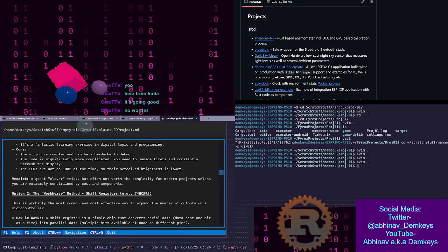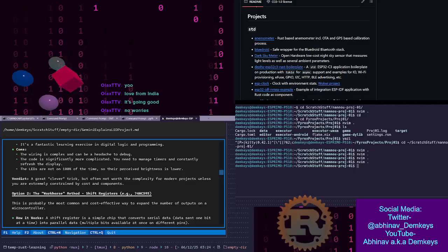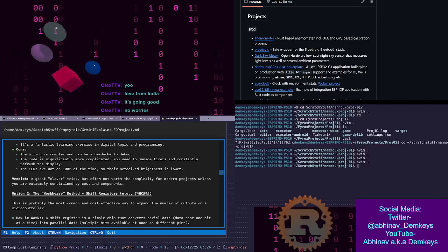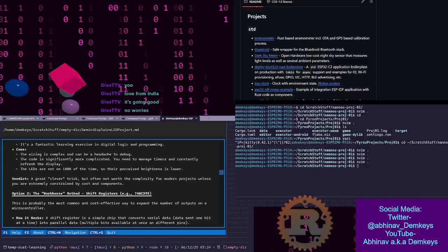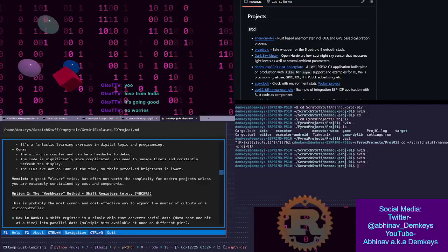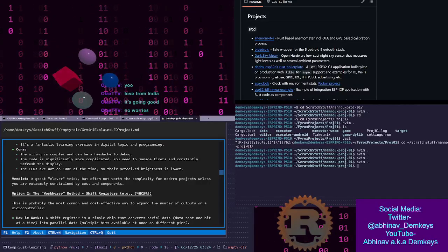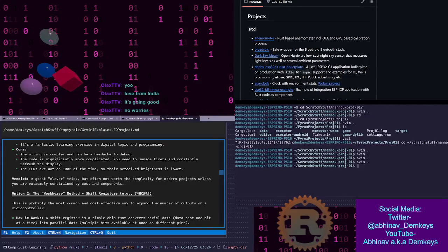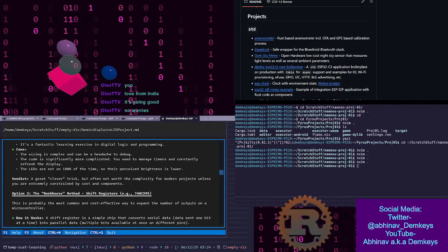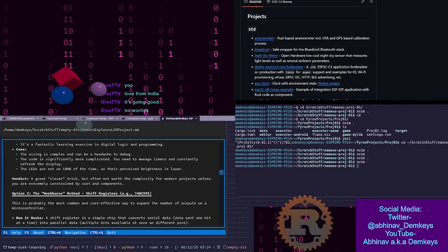It's great, especially for digital circuits. You don't want to be using this for circuits that pull too much current, because that current is then going to be going through the optocoupler, and if it's not built for that level of current, then you're probably going to damage the thing.